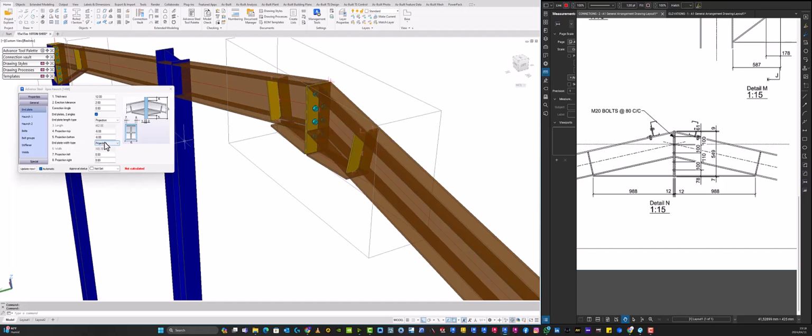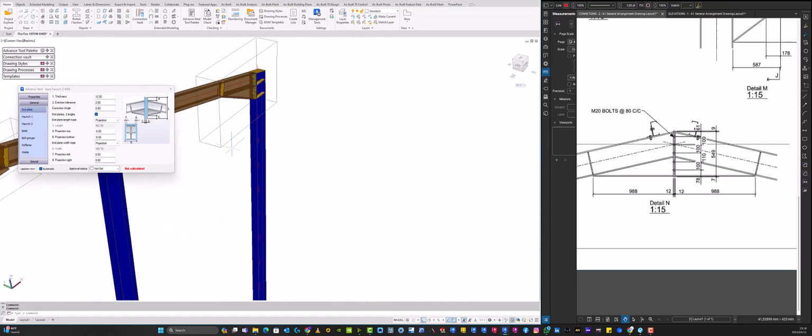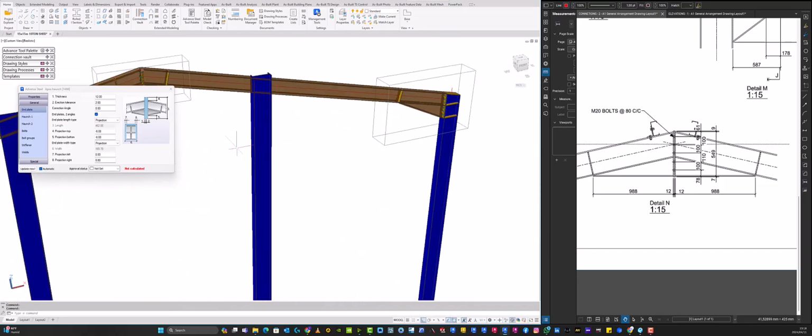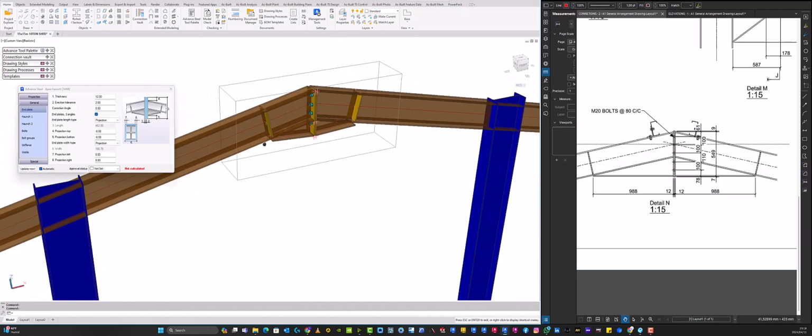So we leave it at projection, and if you see, these are the directions. So your projection to the left, it's item number 7, that's 0, so it's flushing. Projection right, which is 8, it should be 0 because it has to flush. Okay, then on this part we are done. Then we go to the second thing to edit, which is haunch 1.